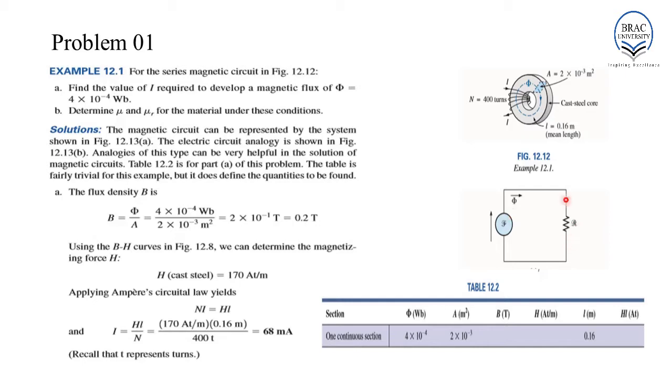Now, when you solve problems based on magnetic circuits, always write down a table like this. Then you can fill in the given details in the question paper, and looking at the table, you can understand what are the variables which you need to determine. For example, by looking at this table, we can say that we have to determine B, H, and HL.